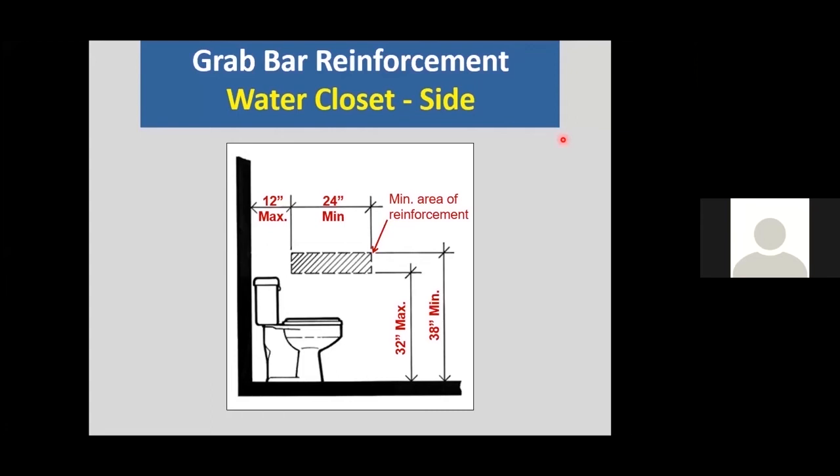That is if there is one, let me say this right: there's one bathing fixture in the unit. It is a shower and it measures 3 by 3. What we're looking at here is that it's the only bathing fixture in the unit, so it has to be considered, quote unquote, usable. And if someone opts for the 3 by 3 size, we put the reinforcing in for a seat because we are building the framework for a transfer shower.